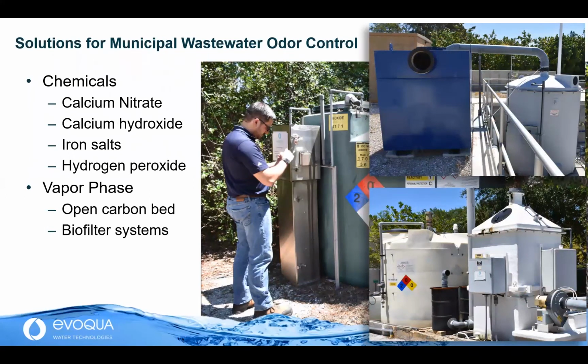Now, odor control also has a wide range of chemical-based solutions too. The chemicals are typically held in a tank and they're inserted into the waste stream at pump stations along the pipeline. And this is illustrated above with the technician standing in front of the green tank. The chemicals you see listed on the side, along with others, adjust the pH levels of the effluent, and they can mitigate the levels of hydrogen sulfide, or H2S, or as we kind of more think of it, the compound that puts the U in wastewater odor.